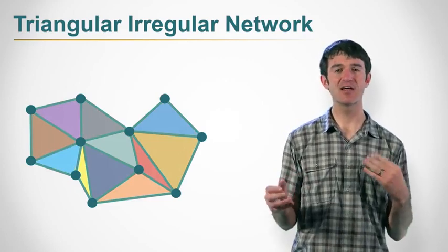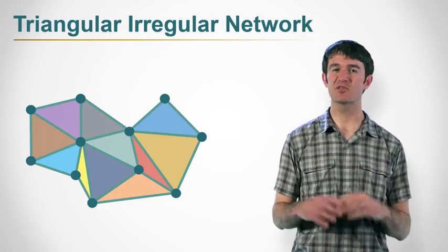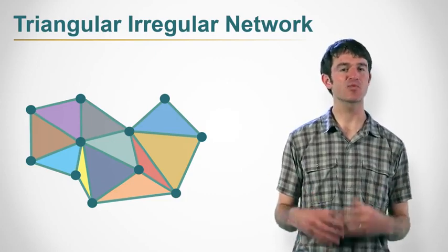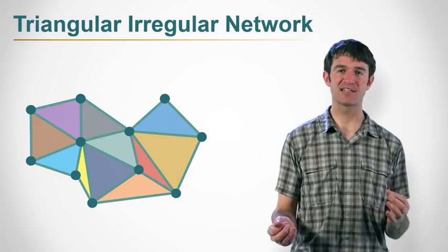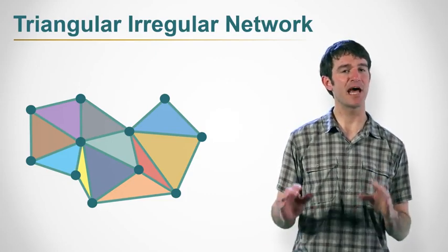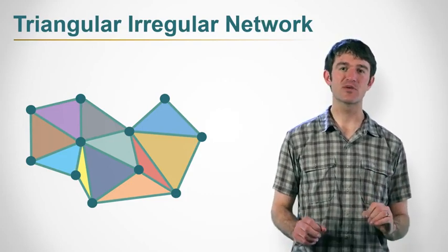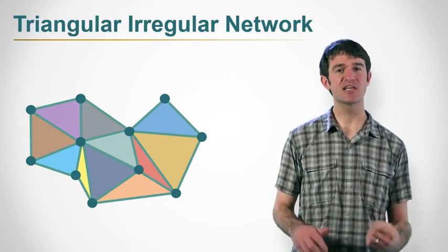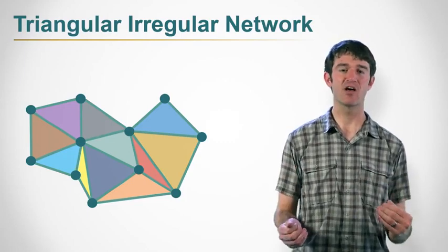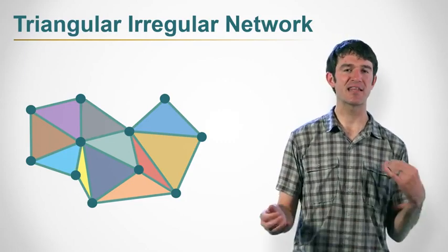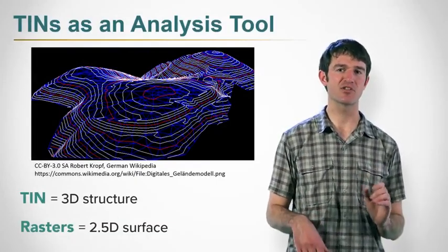These surfaces have area, slope, and direction associated with them. One of these triangles exists between each set of neighboring points, which is where the name Triangular Irregular Network comes from. It's a network, or set of connected edges, that forms triangles, but without a defined pattern that lays out where each triangle is. It's irregular. Once we create that network and associated surfaces, if we want to infer the unknown value of a location from the values we have, we can just find the height of the surface at the x and y coordinates we're interested in.